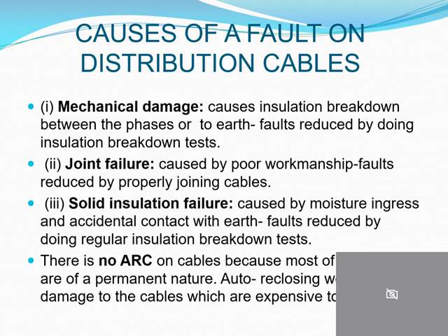For cables, we say that we should not have an ARC. And what is an ARC? An ARC is an auto reclosing system. And what an ARC does, you put it on your overhead lines, which is your transmission that we discussed, or even on your distribution lines, because the causes of faults are similar for the two. And an ARC you put in there so that for the 90% of faults which are not permanent, those ones that are for a short duration, we can make sure that we don't isolate that system permanently.